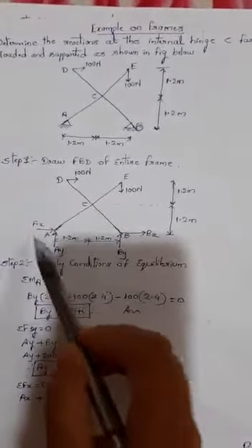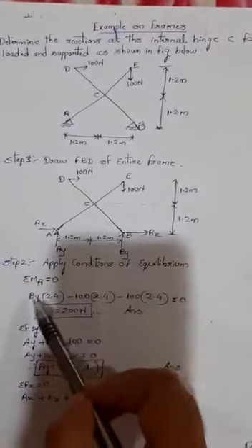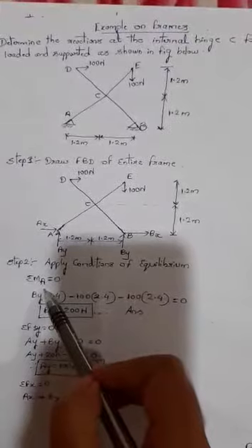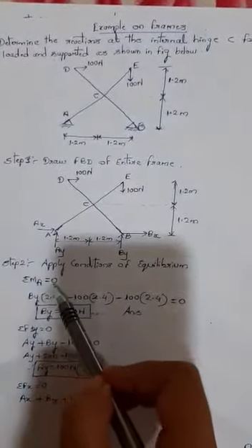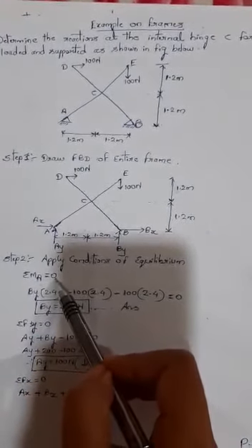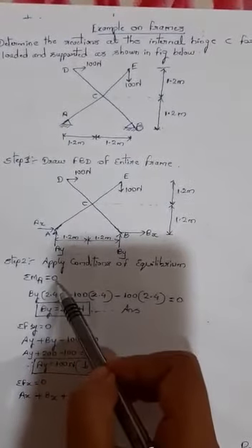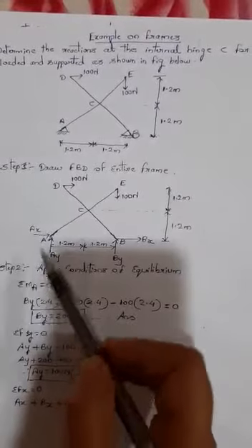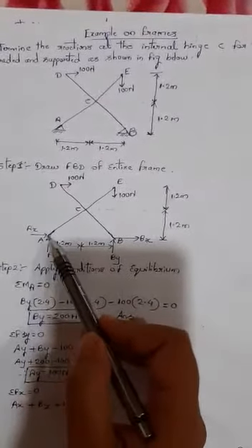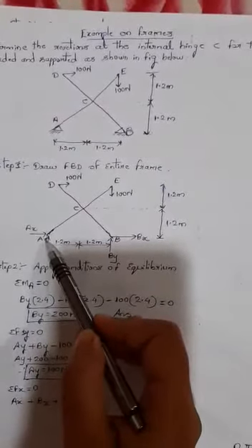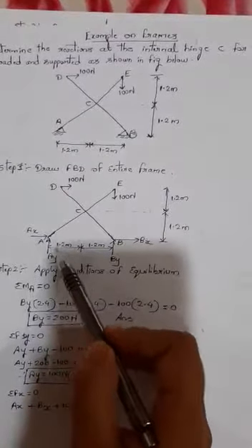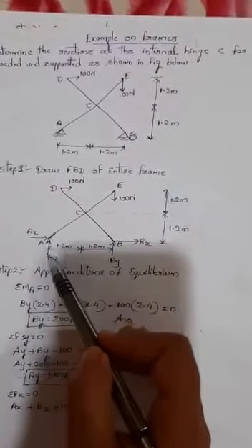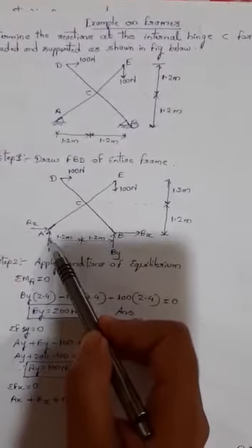body diagram. On this entire free body diagram, first I will consider moment at A. So considering moment at A equal to 0, which is a condition of equilibrium, now we'll see how the reaction forces will be acting at A. At A you can see Ax and Ay are passing through A itself. So what is the perpendicular distance? It is 0. So moment of these two forces will be 0.